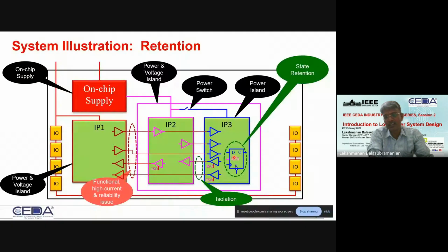The same state I can restore in one clock cycle or less, right? So this is a way to restore the state, but it doesn't mean they all operate without power supply. Only small sections of the device, a fraction of the entire circuit, may be powered to keep those states safe, to keep the previous state. But the rest of the circuits are all off, so power is still saved. At the same time, I'm able to wake up very fast when I'm powering up and start working seamlessly.